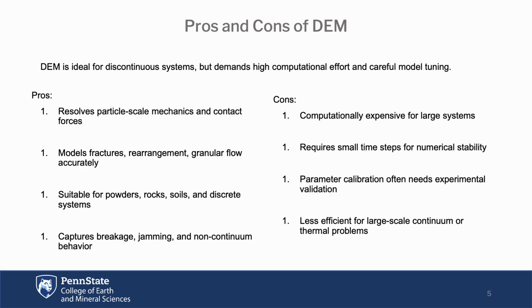One of DEM's greatest strengths is its ability to simulate particle-scale interactions explicitly. Each particle is treated as an independent body governed by Newton's law, contact forces, damping, and sometimes cohesion, that are calculated directly. This makes DEM highly effective for problems involving granular flow, soil behavior, powder compaction, and rock breakage.